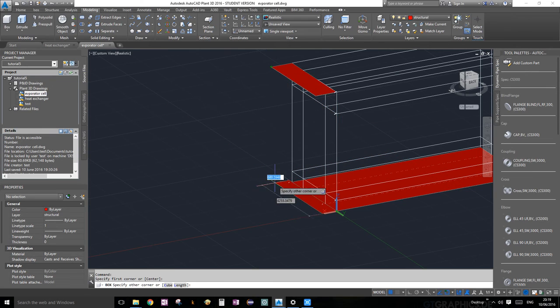Nope. Okay, so what you can do is type 1000 here and press tab. It will jump onto the other one, and you can choose that one. We know that is 4000, so we're gonna type in 4000 and press enter, and then it's gonna ask you to do it this way, and then you can choose your thickness 10.